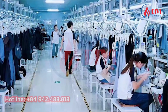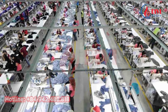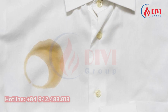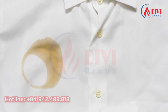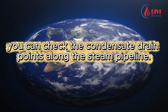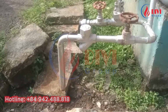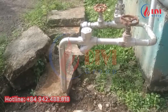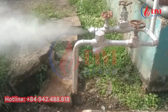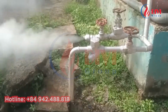In garment, laundry, and ironing factories, steam is injected directly into the products. If the steam is wet, water droplets can stain the garments. Therefore, installing a steam separator before each ironing line is essential to ensure that the products are not damaged by water. If you suspect that the steam from the boiler is wet, you can check the condensate drain points along the steam pipeline. If condensate flows out, it indicates that the steam is wet. The more condensate that is discharged, the wetter the steam. In such cases, installing a steam separator is absolutely necessary and highly cost-effective.